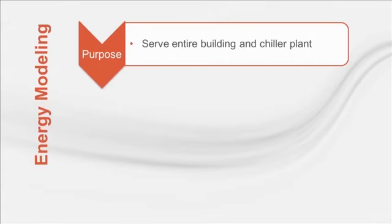A building energy model's purpose is to help owners and designers make sound investment decisions. Although a typical model shouldn't be used to predict absolute energy use, an accurate model can help designers determine the best options to deliver long-term cost and performance benefits based on the purpose of the building. Final purchasing decisions should be vetted with proper justification. The same is true for selecting a chiller or chiller plant in the early planning stage.